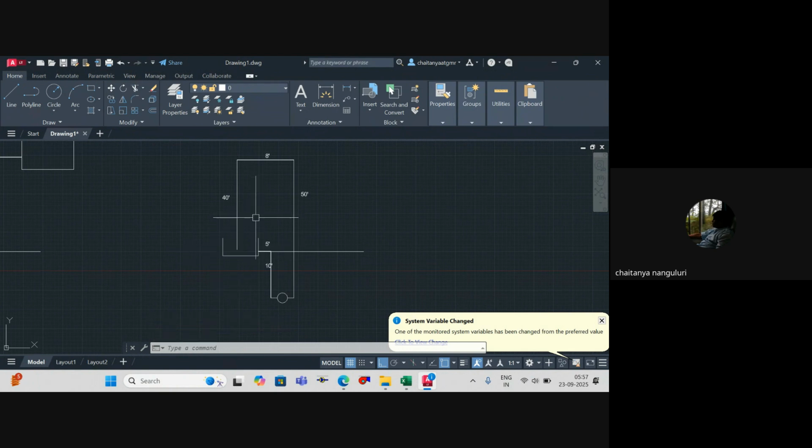You agree? Okay. Now from here to here, if you see, automatically the water will come till here. So even though you have the pump at the bottom or any location, your equilibrium will happen. The pump will get the additional 10 feet anyway. So the additional work it has to do is only 40 feet. You agree?